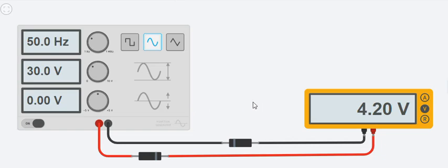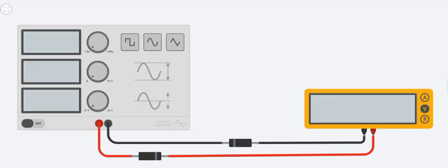So I would have loved if you have an AC meter in this application, so that we can also measure what's going on the AC side. So the point here is, by the time we are done with the full wave rectifier, you will not need to be careful of which point is positive or which point is negative in the AC. The rectifier itself will adjust itself. That's one. Number two is that there is a number of stages that comes after the diode rectifier stage that allows the voltage to climb up a little bit again.